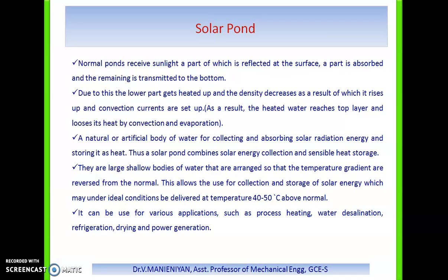The solar pond promises to be an economical alternative to flat-plate collectors for energy storage, by employing a mass of water for both collection and storage of energy. The energy is stored as low-grade heat, at 60 to 100 degrees Celsius, in thermal form. In itself it might be suitable for a variety of applications, such as heating, industrial purposes, and likewise conversion to electrical energy.